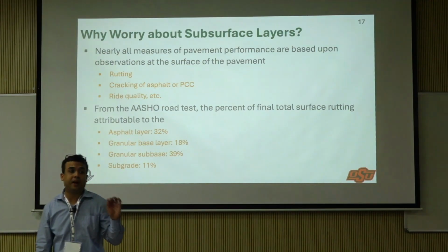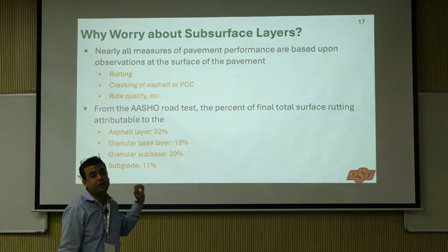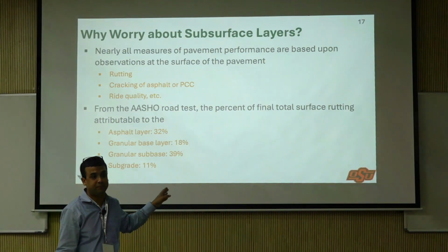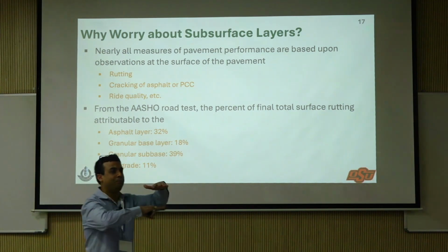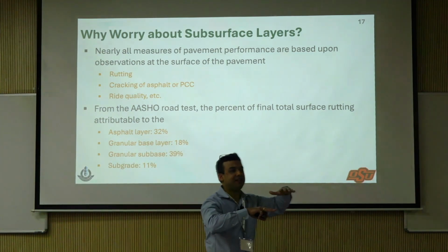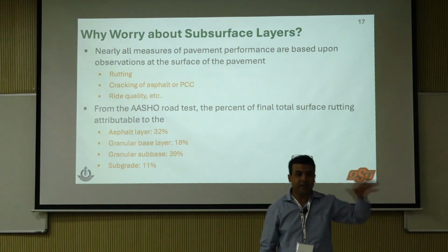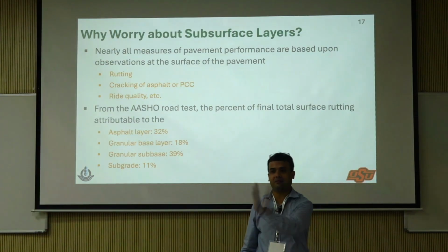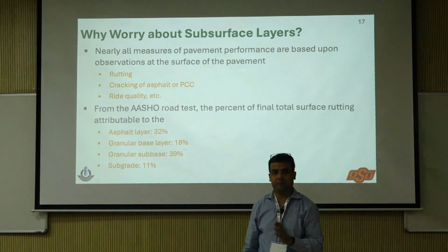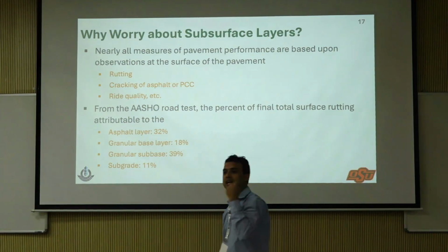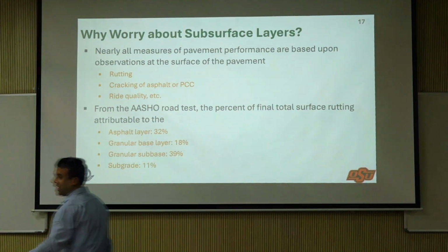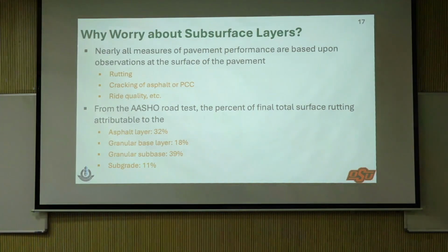Now I will tell you one thing, it is possible to mask over this problem sometimes by building a very thick concrete slab or doing a really big cement stabilization of a base and then building an asphalt layer. It's possible to sometimes overcome this. But then the problem is, are you doing your job as the engineer to do the most economical, sustainable, resource efficient design? The answer is no, right? So that's the reason you need to look into that.